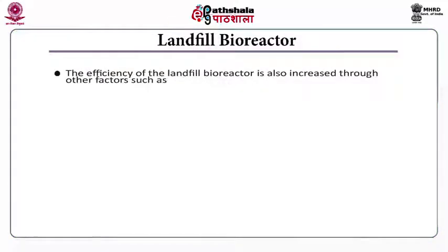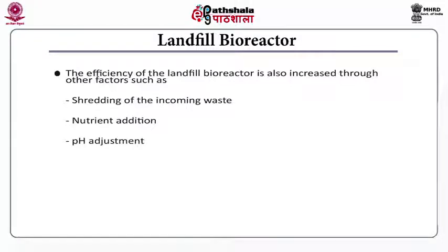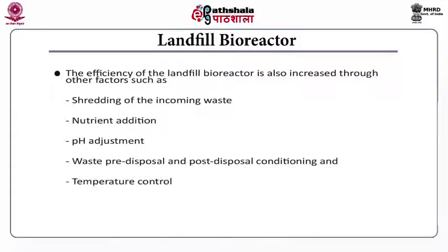The efficiency of a landfill bioreactor is also increased by other factors. Shredding will improve the degradation and accelerate the rate of degradation. Also, you can add nutrients through the incoming waste stream, or through other modes of maintaining moisture. You can adjust the pH, and waste pre-disposal and post-disposal conditioning and temperature control will also act as factors to accelerate the rate of degradation within a landfill bioreactor.